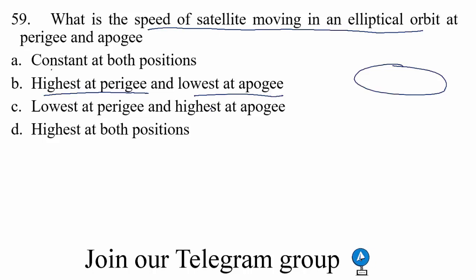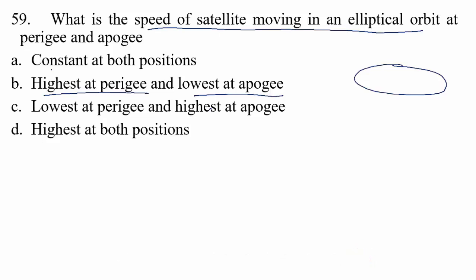And one more thing you have to remember is uplink frequency will always be maintained higher when compared to downlink frequency. Why are you not going to maintain uplink and downlink frequency the same? Because it is going to cause a distortion. So you maintain uplink frequency different from downlink frequency, but greater than downlink frequency, just because satellite communication is power limited communication. So based on this, I will be getting option B as correct.